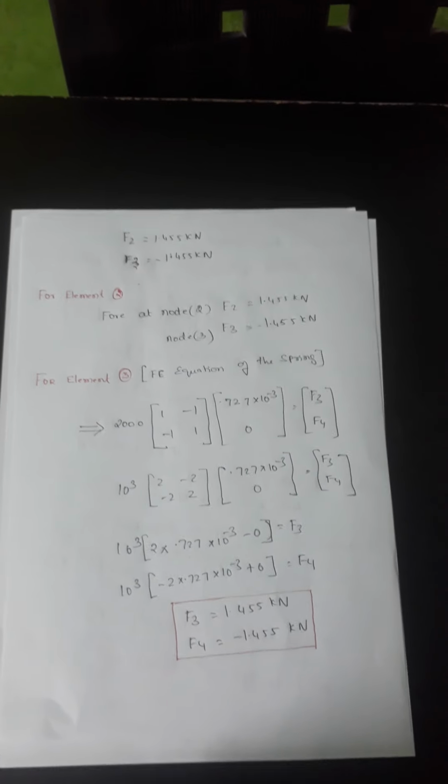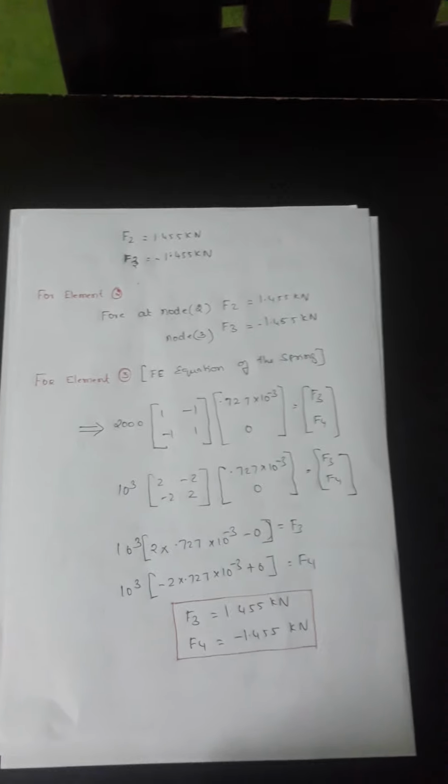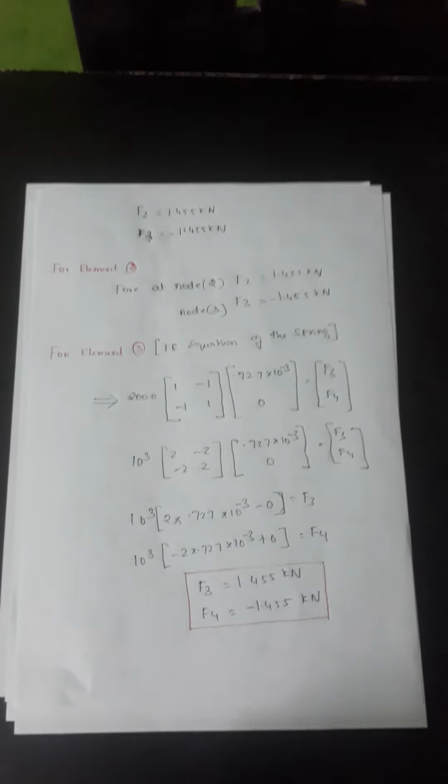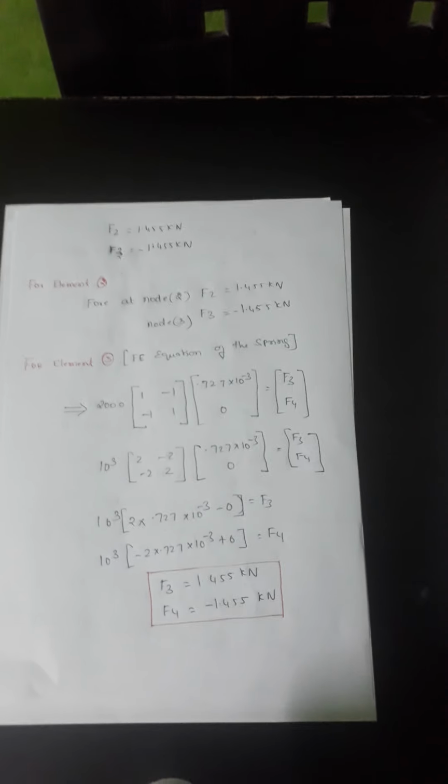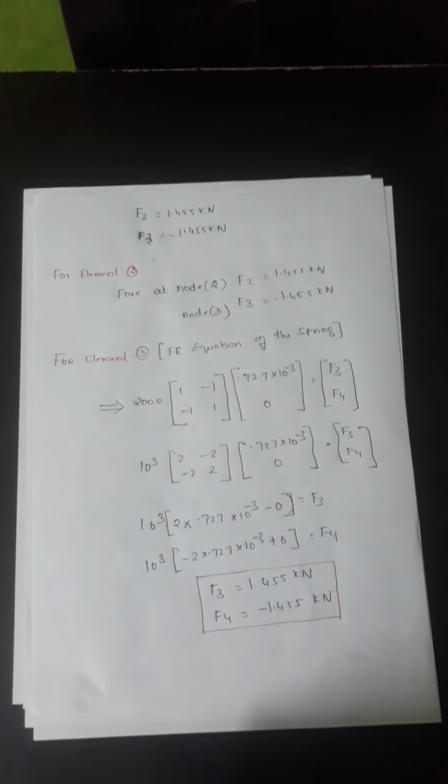Please remember that. If you want to find both the forces, the same finite element equation should be used. First, the self weight is neglected and you find the displacements. Next, you don't give any nodal forces, just write the nodal forces. The same equation you substitute, and you will get 2 equations and 2 unknowns, so the algebraic equations can be easily solved. So don't confuse body force and nodal forces. Nodal forces are due to the applied force, and body forces are due to the gravitational force.